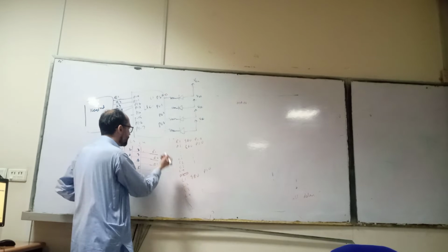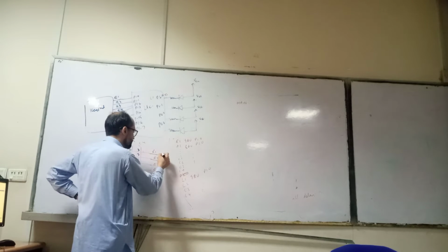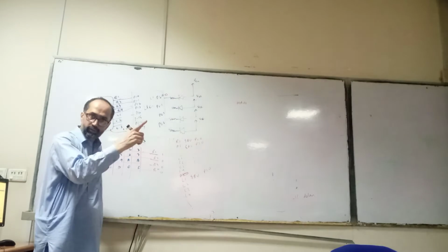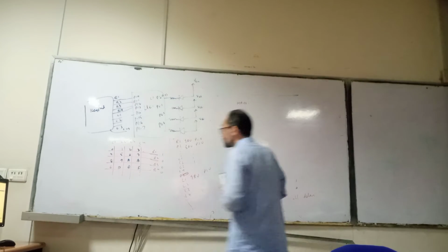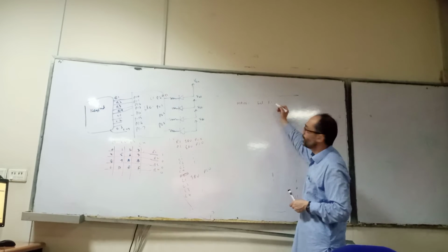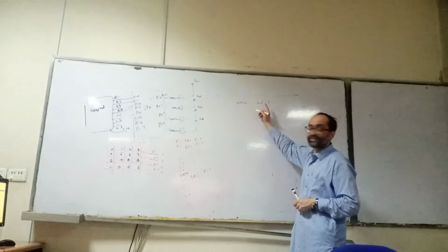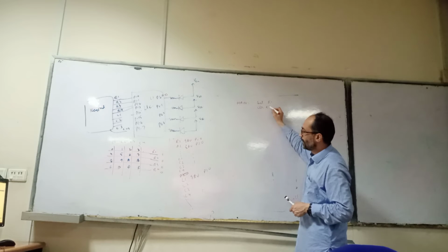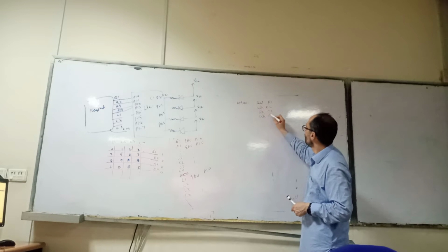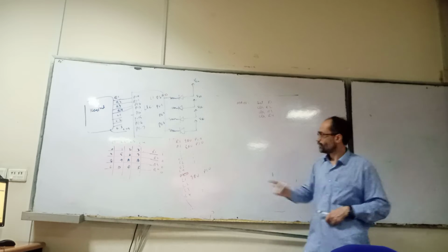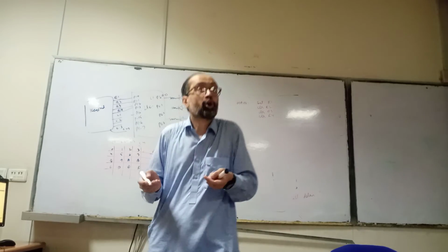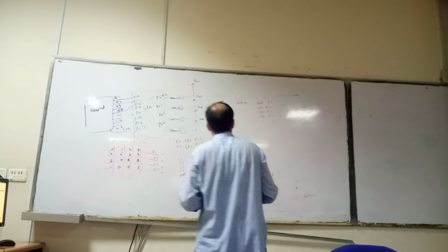The code that we are sending is 1000. So we are driving the rows. When we are driving the rows, what will be the code? Set R1, clear R2, clear R3, clear R4. So now we are driving the rows. Now we need to scan the columns.